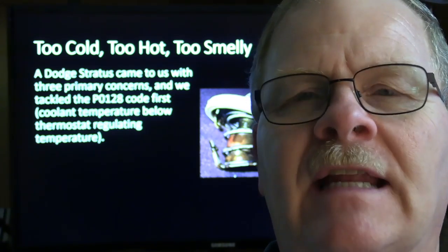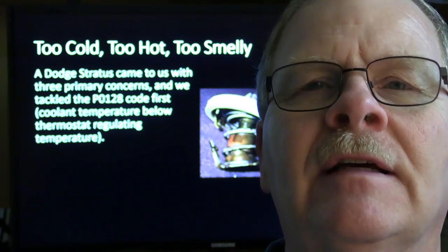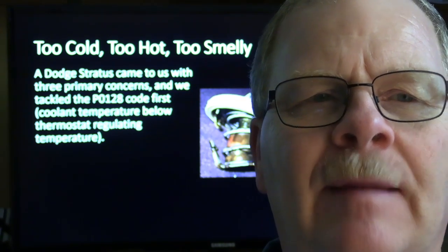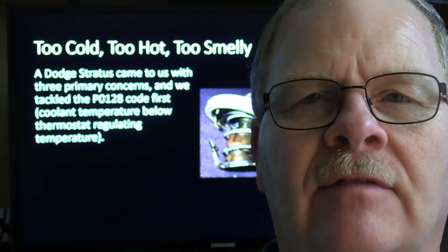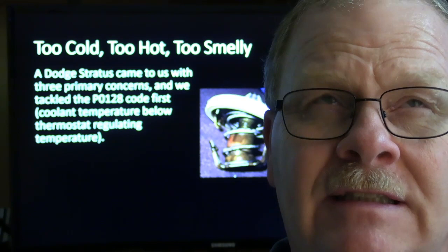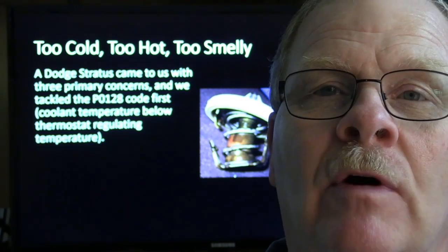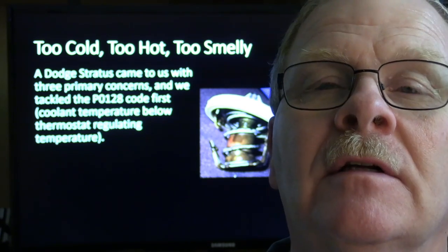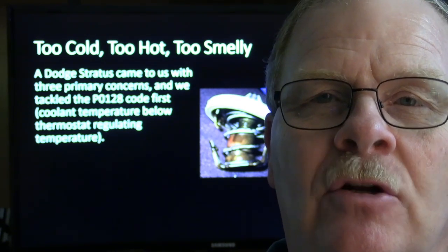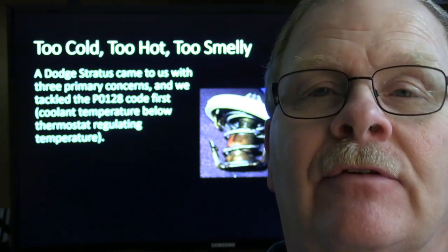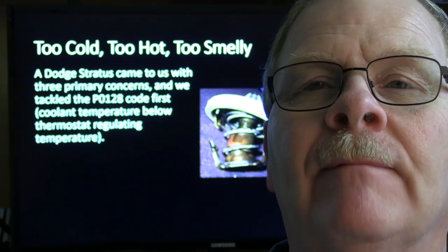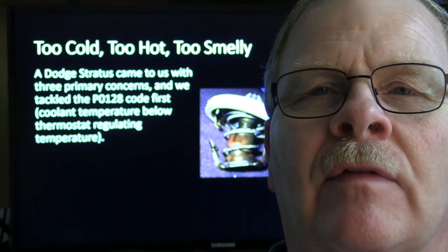They put a thermostat in it. It still threw a 125, and oddly enough, that particular car never threw any kind of a code for an oxygen sensor heater, as I remember. But what it did do was throw that 125 code until the oxygen sensor heater problem was straightened out. After that, the 125 code went away. And so there's a little bit of something going on there.